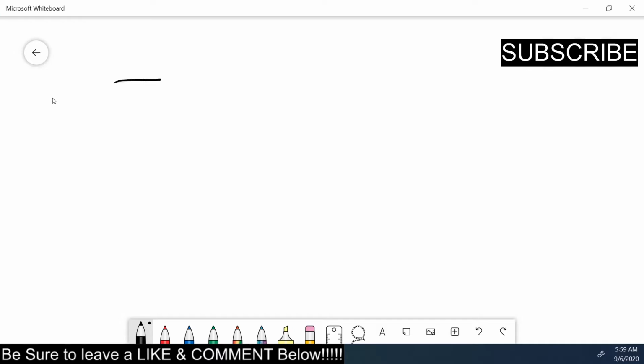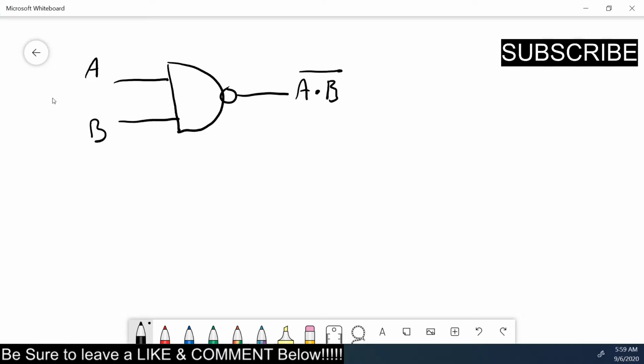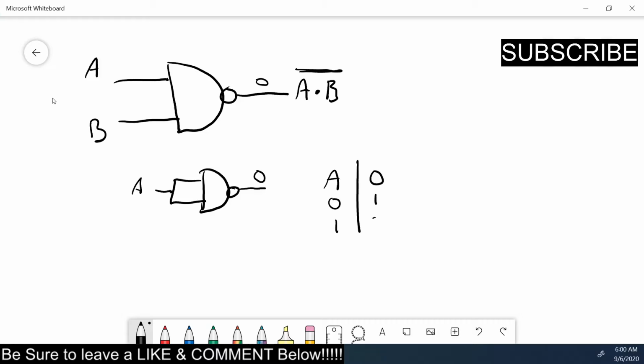So I have a NAND gate like this, and I have my output, and this is A, and this is B. Whatever this is, it's going to be A and B, and it's going to be the opposite of it. Well, if I take a NAND gate like so, and I tie A and B together, and I have an output, I will have a truth table like this. If it's a 0, it's a 1. If it's a 1, it's a 0.